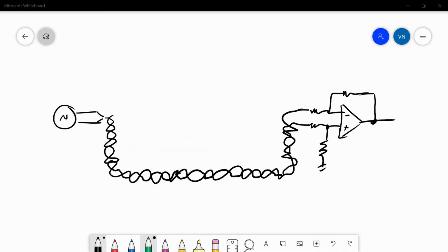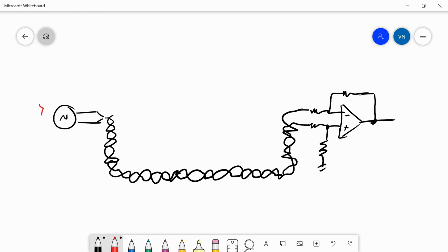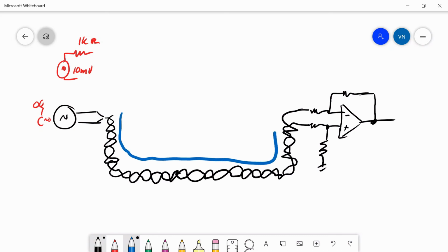So what is common mode rejection ratio trying to tell us? Let's imagine that you've got a recording studio and you've got the singing artist belting out a song into a microphone. The microphone is just a voltage source that generates a couple of millivolts of signal, which it delivers to the line through about a 1K ohm output impedance. Now it goes into the line here and it has to pass under the floor and then make its way into the recording section of your studio, where it gets amplified by a differential amplifier, and that gets put onto tape.